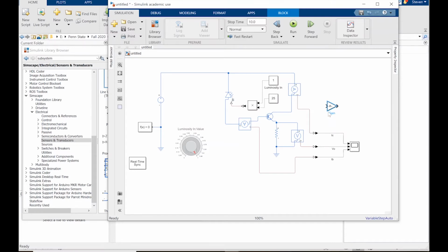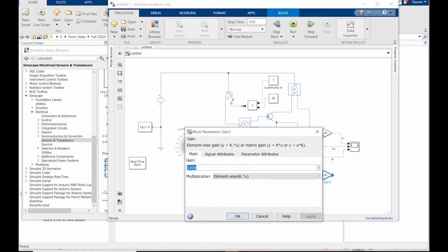So I just went to the Simulink models, added a gain, or maybe I just typed gain and it popped up. Now I realized that it's not just going to let me plop the wire in, so I'm moving it out of the way, putting the gain back in, and reconnecting it. I want to keep the wire that's labeled on the scope side so that it maintains its label. Now I'm right clicking and dragging down. This one I'm going to do 10,000.